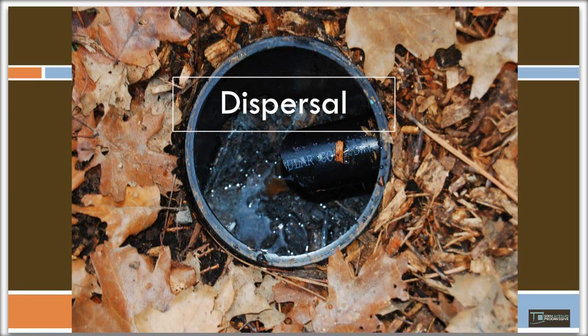And it's coming out either all at once from a bathtub or a shower, or it can come in short surges that are pumped under pressure from a laundry to landscape system. There's also drip irrigation or sometimes a pump effluent system where you can control the dispersal a little bit more. And so you want to make that decision on how you disperse it.